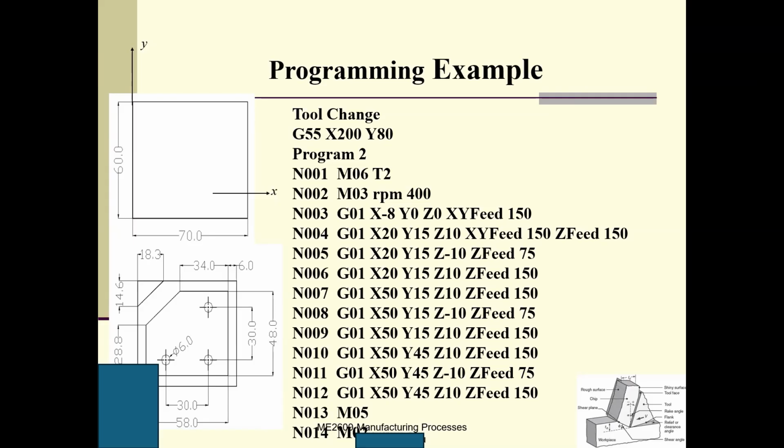I'm here, this one. G0 x20 y15 z10. Z10, I'm going to move my tool here. And then I come down, right? So I just move above, this is the position. And then I move down to give the actual depth. So actual depth, from Z10, I go to minus 10. Right? So minus 10, my drilling tool will rotate and drill a hole.